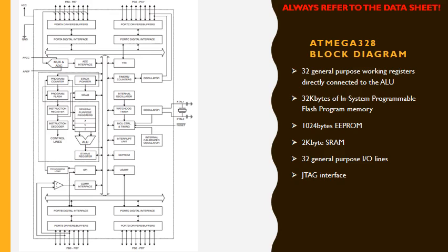I'm not done yet. Can you locate the AREF pin? AREF, it's outside. Remember, we've seen it. So it's not those. It's definitely not VCC and definitely not ground. And there's the AREF. It's physically connected to what? Can anyone read? To MUX and ADC. So it's physically connected to the ADC. Hence, I didn't lie to you.